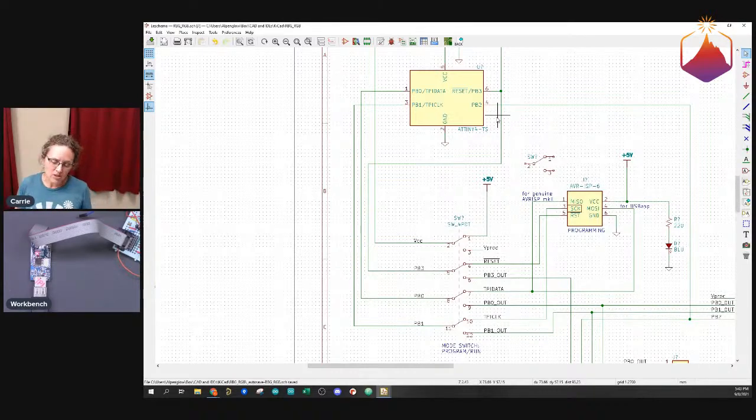So generally it's good practice to separate out those lines, leave them just for programming, and use all of the other pins for circuitry. Well, when you only have 4 pins to choose from, and 1 is your reset pin, you really can't use that for other circuitry. You sort of can with this chip, I can get into that later, but you don't want to accidentally be pulling your reset pin low and resetting your chip in the middle of its program, right?